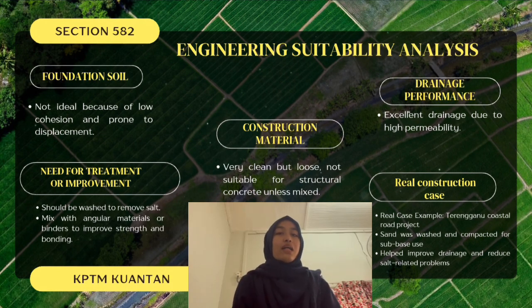Okay, now let's look at the engineering suitability of beach sand. As a foundation soil, beach sand is not ideal because of its low cohesion, which makes it prone to displacement. However, if compacted properly, it can still provide support for light structures like footpaths or pavements.